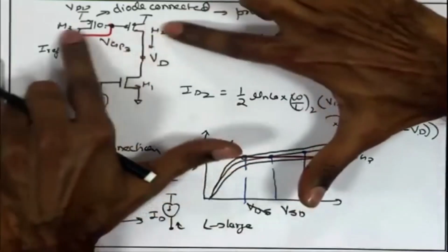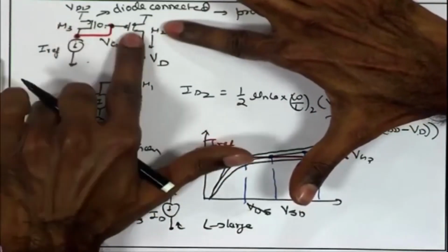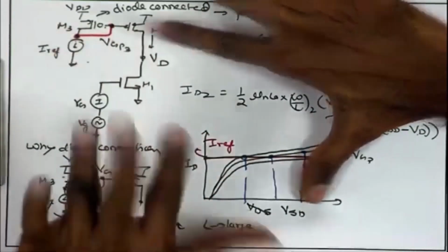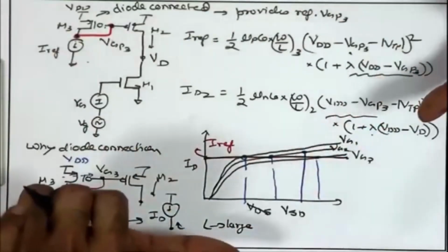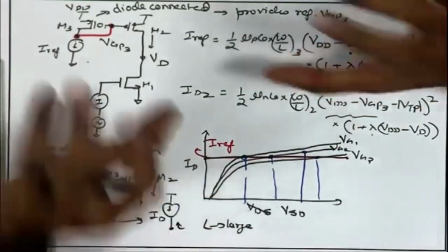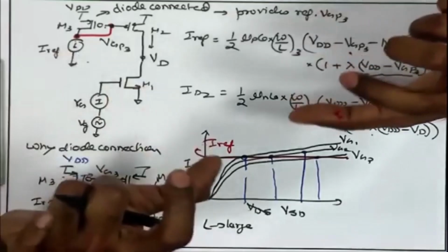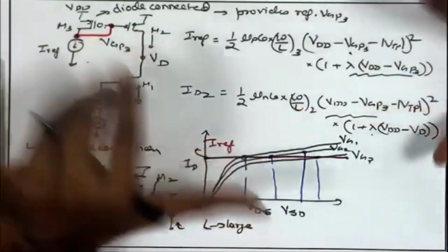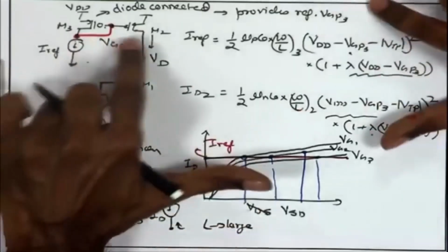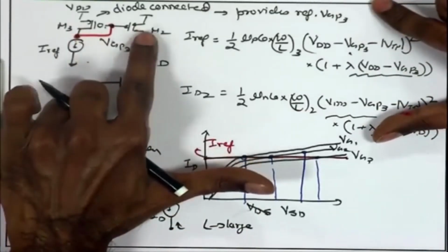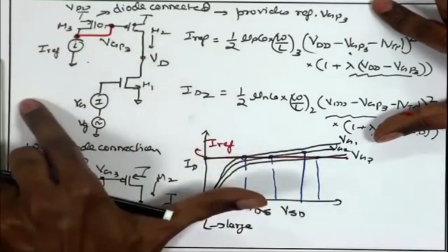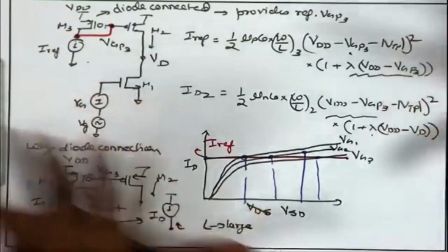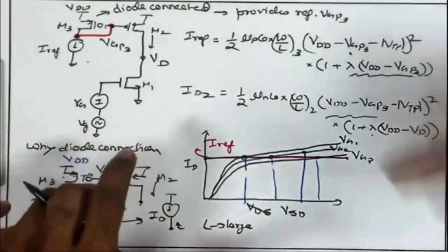How do you do the physical layout of two PMOS transistors that you want to match? Likewise, if you are having a differential amplifier that we will be going towards very soon, you need to match the NMOS transistors of the differential pair. So, there we have the concept of the common centroid layout through which we can ensure good matching between two PMOS transistors or two NMOS transistors, but we cannot ensure good matching between NMOS and PMOS transistors.